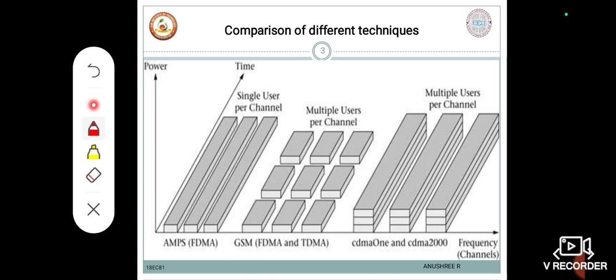However, the frequency planning in the PCS bands becomes much more problematic if one considers inter-system issues. The three possible cases to consider here are: first, if the two systems are both CDMA, then geographically neighboring systems should not affect one another. The second is that the other system is either an NA-TDMA or GSM system operating in the adjacent geographic area within the same frequency block. The third problem is that frequency coordination is again necessary in conjunction with the consideration of the type of pre-existing service.